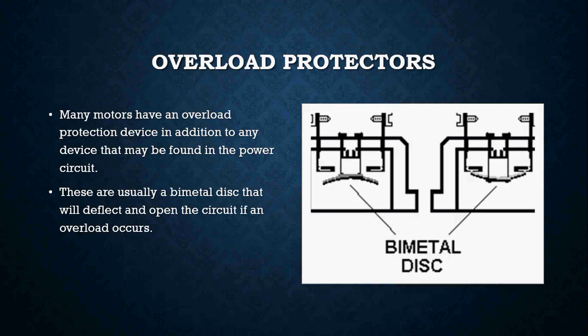If the motor is really warm to the touch or hot, chances are the thermal overload inside the motor has taken the motor out, and it's not going to work until the motor is cooled off. Or in some cases, the bimetal disc just does not reset itself and the motor needs to be replaced.